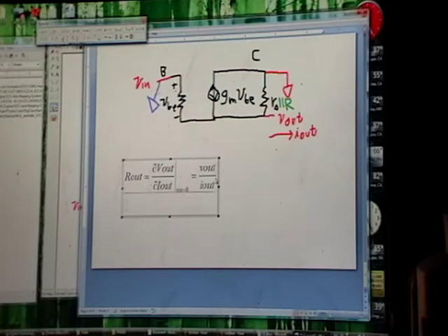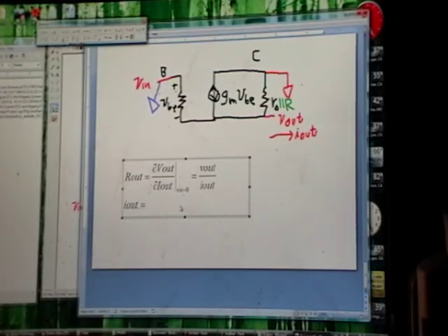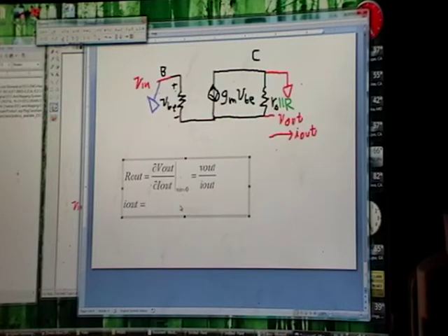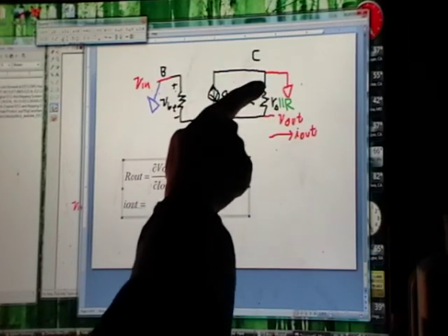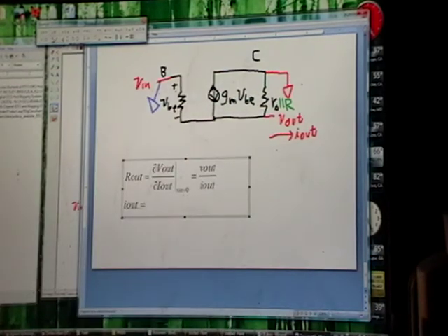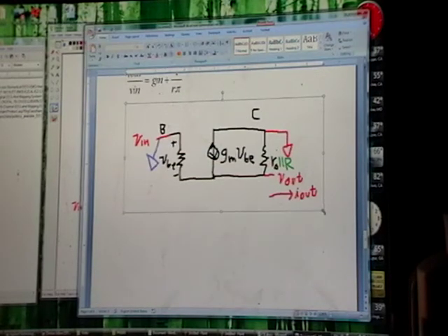So our first goal is, since it's not immediately clear what R out is, we have to set up an equation, and we have I out. I like to start with a current. If there's a current in this equation, I generally like to set that current equal to something and do KCL. So I out equals the current across here. And now that V out isn't ground, we can't ignore this. So that is equal to... shrink this a little bit.